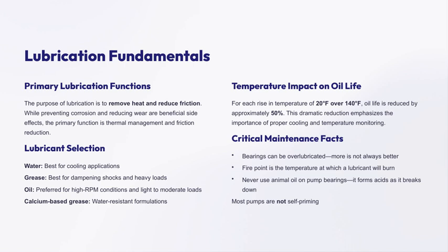Now, an important point to remember is how temperature impacts oil life. For every 20 degrees F increase above 140 degrees F, the lifespan of the oil can be cut in half. This highlights just how critical proper cooling and temperature monitoring are to maintain equipment efficiency and prevent failures.